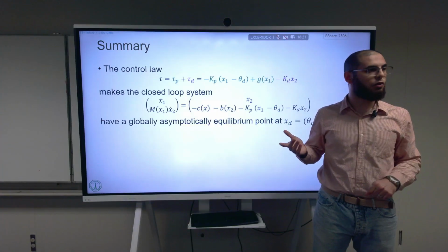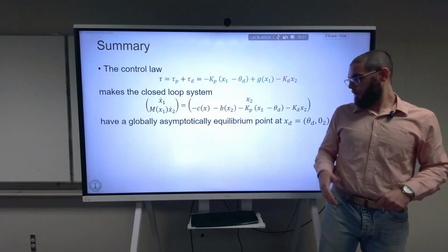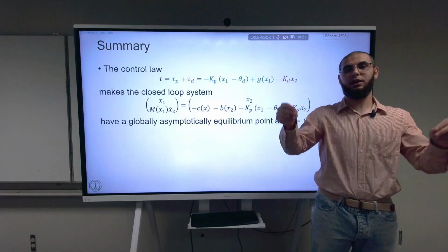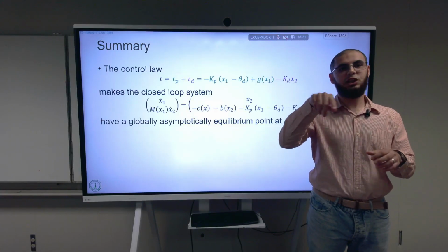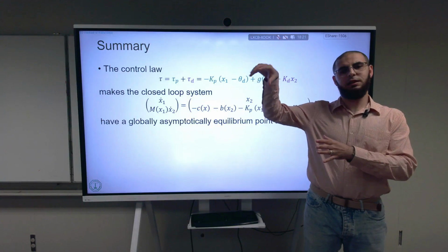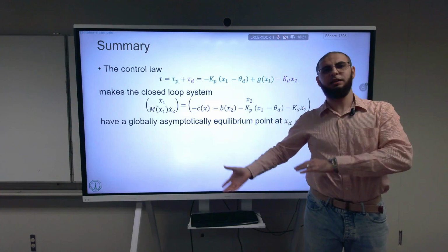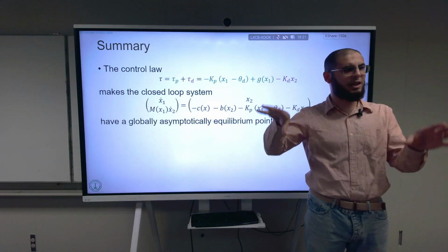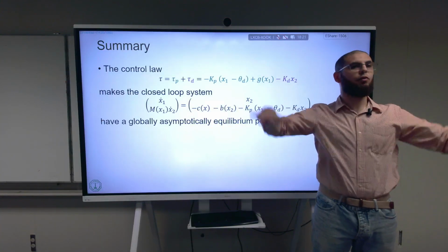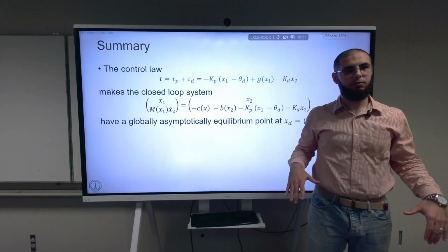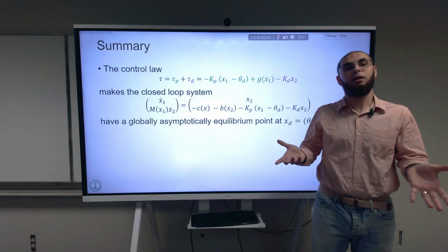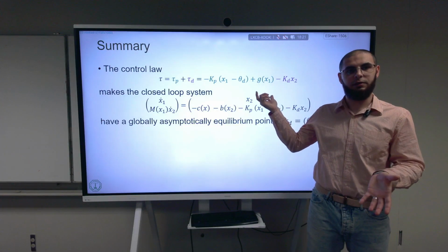How do you get the gravity torques? If you go back, but you need to go really back, you remember that we had an equation for the gravity torques, right? I had the G of x was equal to, there was something that was taking the gravity in the spatial frame, and I multiplied it by some adjoints, and I multiplied the inertia. There was an expression there when we assumed that the whole inertial frame was translating up, it was moving up. We had an expression for the gravity. So if I know what the robot looks like, I can always find what the gravity terms look like.